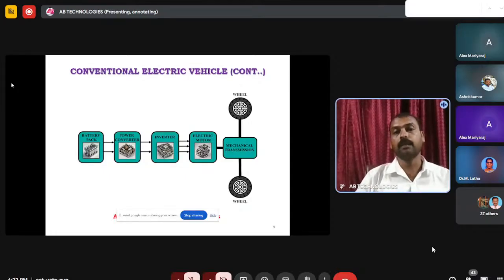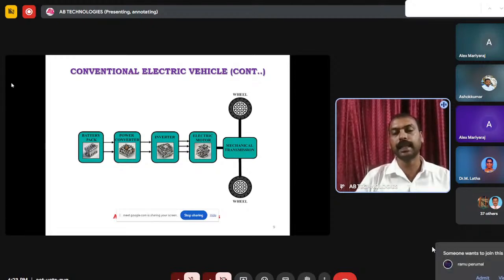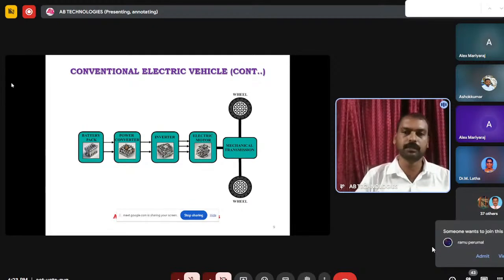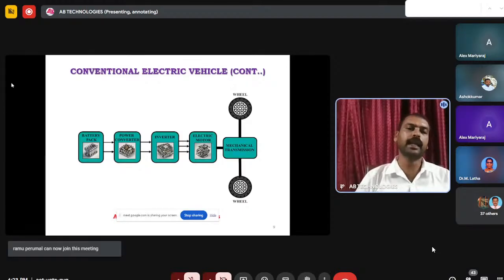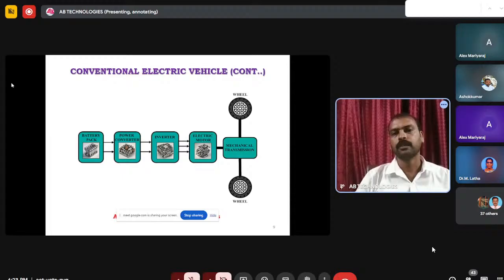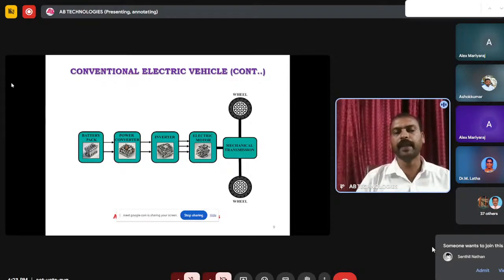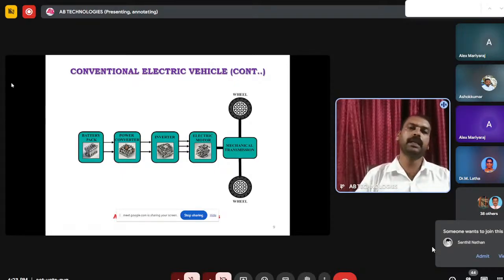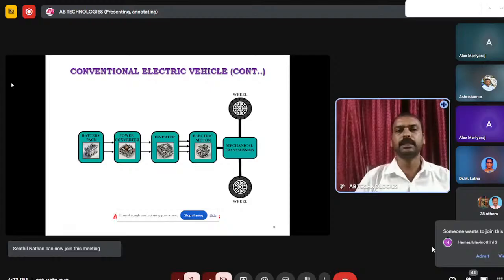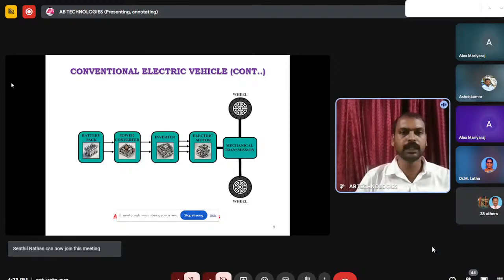So, before the PFC converter, this diode rectifier is also creating a voltage sag problem. That means it's creating power quality issues and affecting the input source. In order to overcome the problem, we have to go for PFC based converters, meaning the PFC boost converter, PFC step converter, interleaved converter. So many converters are there.